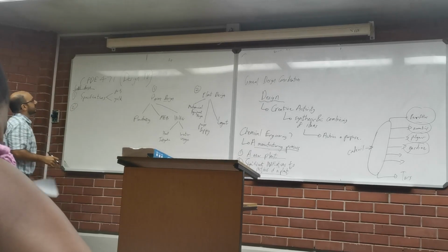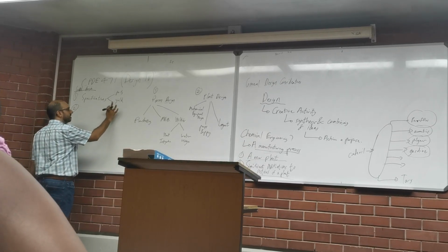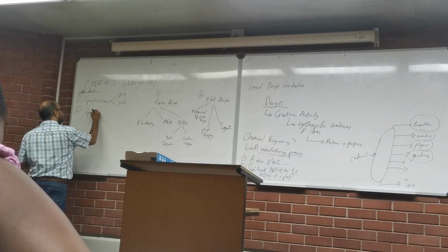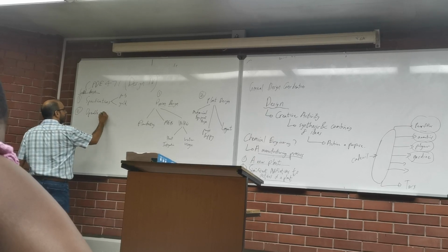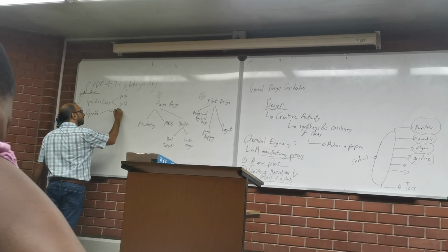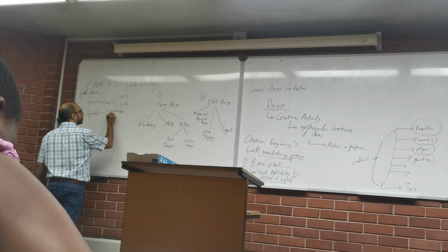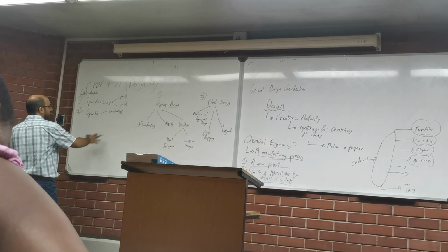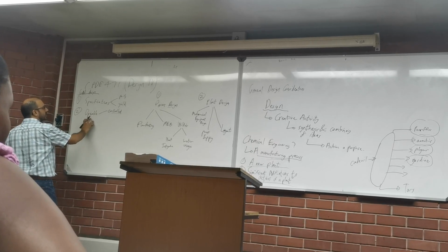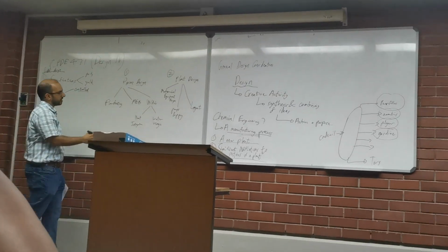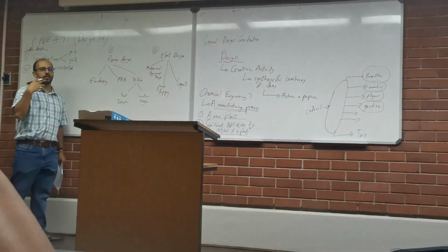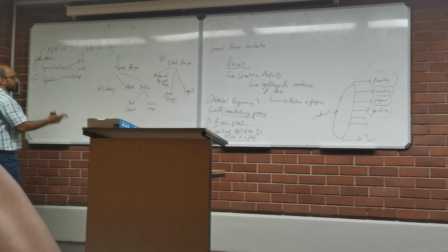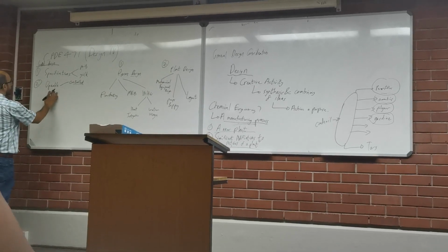Now there are a number of ways in which you can meet those specifications, but that's not the end of the story. It needs to be, firstly, operable. It must be very well controlled. So you have to work out what sort of control measures, valves, fittings, safety measures, etc., you need to actually control every aspect of the process. You need to be able to control how much feed you let into the reactor, how much product you are letting out, through which outlets, etc. So that's operability.